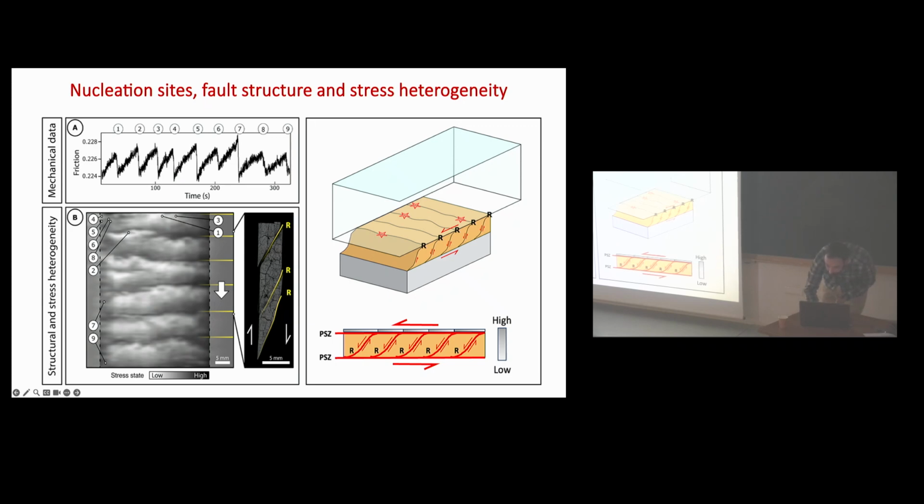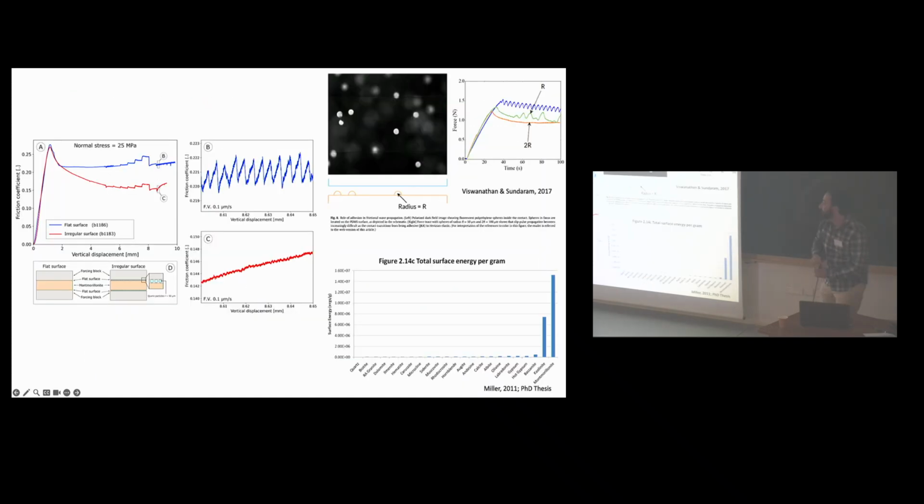And for instance, what we have done is some tests, and since adhesion is more efficient when you have two surfaces in contact that are clean and polished, we use this flat plexiglass block to put in the middle, and we put in between, one that is flat and the other with small quartz grains. This is the one flat, and this is the one flat with quartz grains, and strangely with quartz friction is even weaker, but maybe it is also grain rolling.